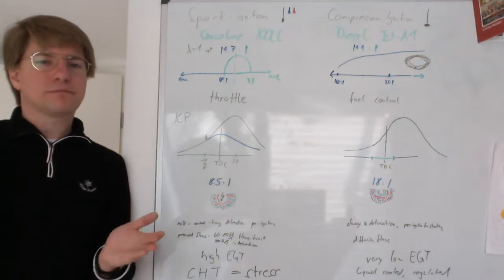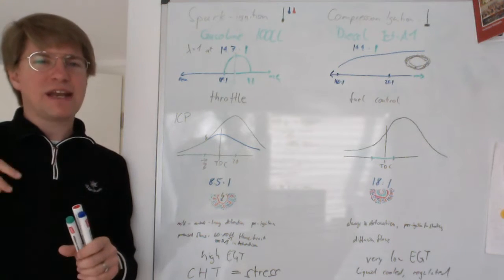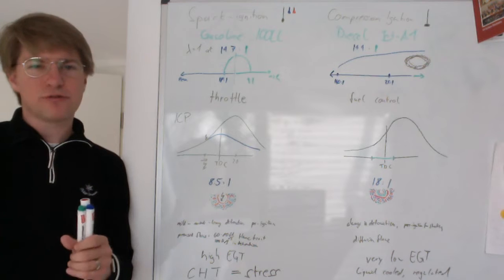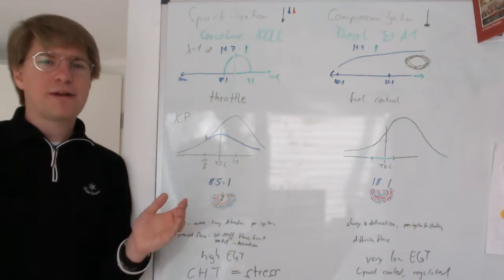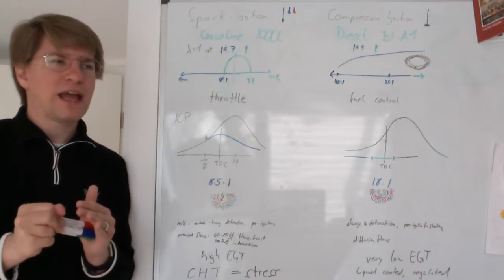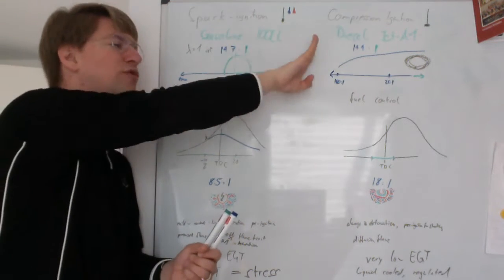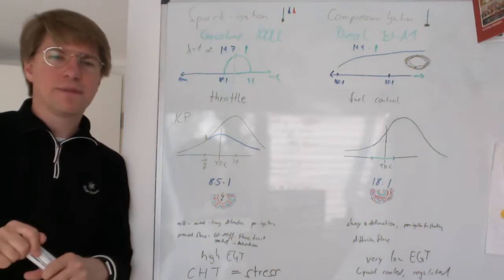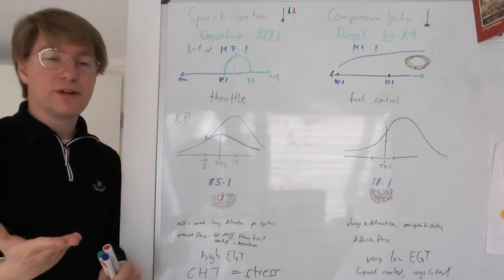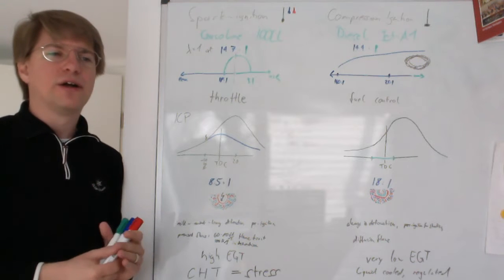So what happens here? We have an excess amount of fuel because we have not changed the fuel to air ratio in volume, and we have less weight of air. So we move over to the rich side of the curve, and first we are losing efficiency, and then we are losing power.